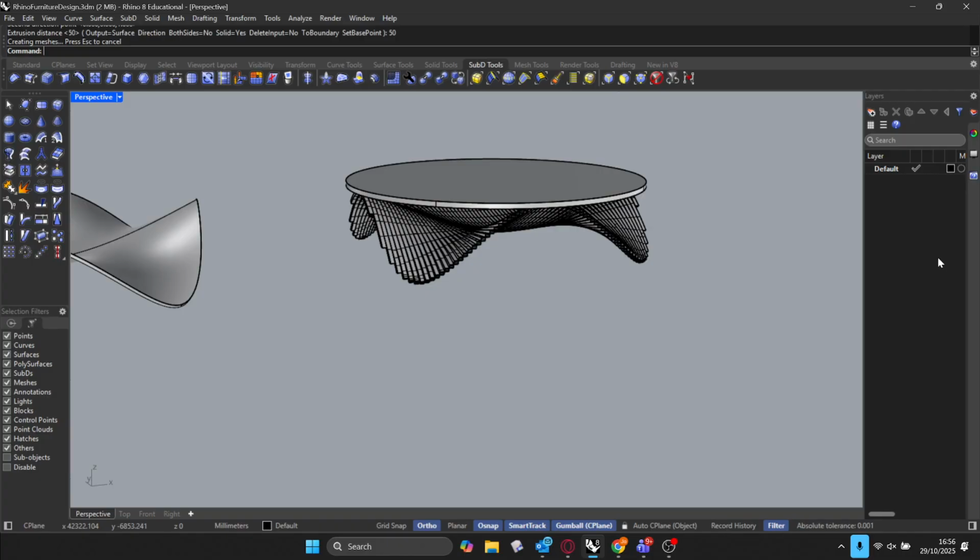So the sub D thing works differently from the normal. Yeah, NURB surfaces and sub D surfaces are very different. Sub D is subdivided surfaces that are more like polygons, and when we hit tab, it subdivides into a more organic shape. I usually model in the non-organic shape so I get an idea of the shape, and when I hit tab, I can see the organic version when it's subdivided.